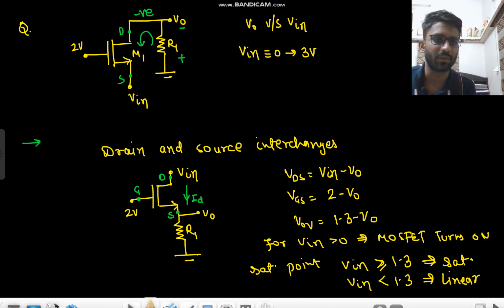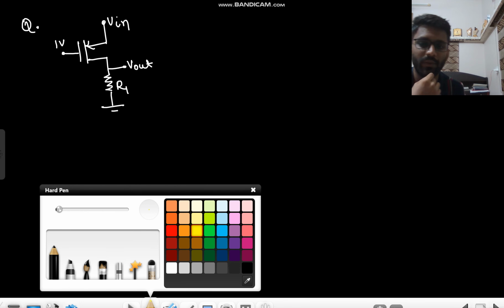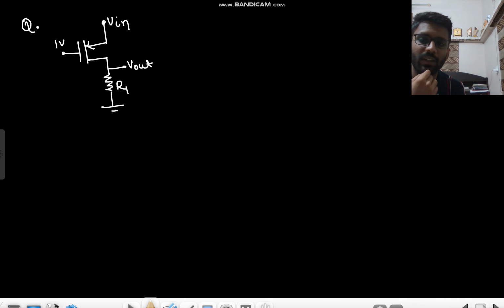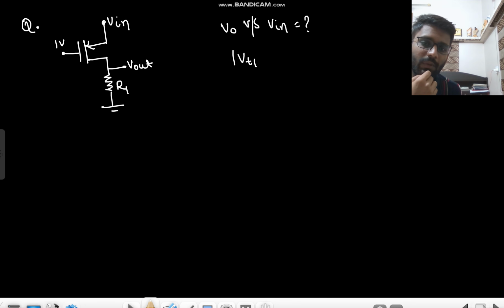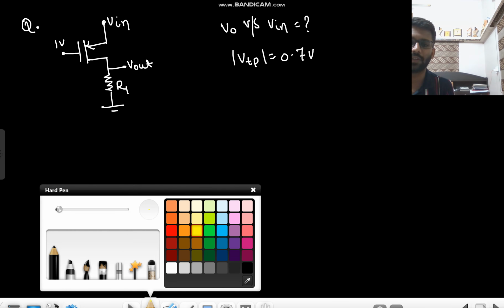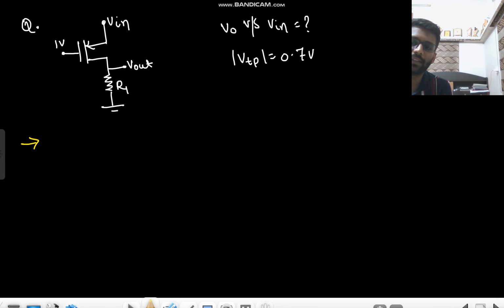Okay, thank you. Hello everyone. Now we will see this question. In this question, again, V naught versus V in we need to plot, and mode of VTP is given to be 0.7 volts. Okay. So now tell me, in this question, will the source and drain be interchanged? This is PMOS.